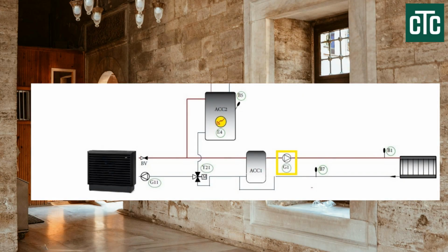The most common system configuration is when the circulation pump G1 is controlled by an external controller. In this case, it makes sense to receive a signal from it to activate the heat pump in heating mode. Without receiving this signal, the system will heat domestic hot water only. Now, let's look at all the components and their connection terminals.